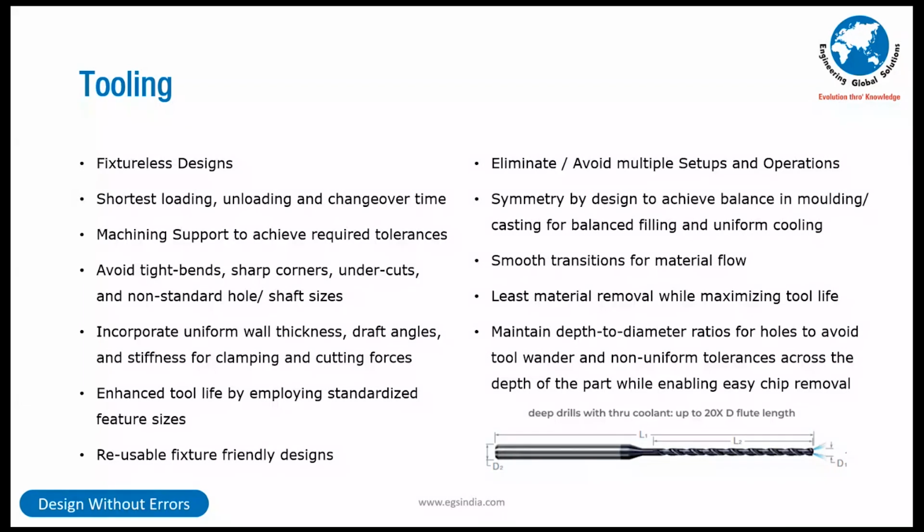I have put 70 microns. Now I am seeing leakage. I am reducing it to 5 microns. Already with 70 microns, I am not able to achieve it. How can I achieve it with 5 microns? Put enough locating pads. Put datum targets on those. Give it to those people. Visualize this, folks. And your clamping pressure comes in. All these have to be taken into consideration. So the machining support has to adhere to this very carefully.